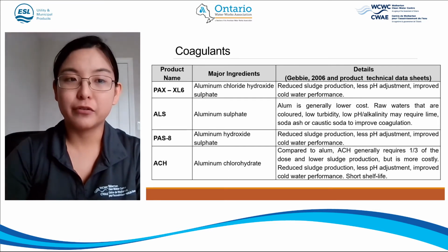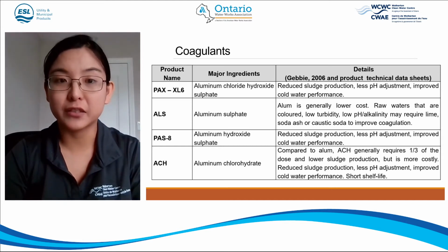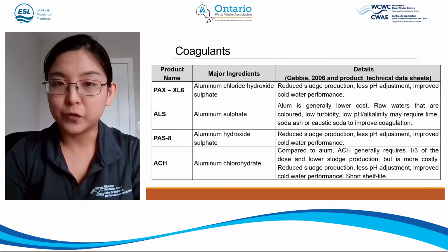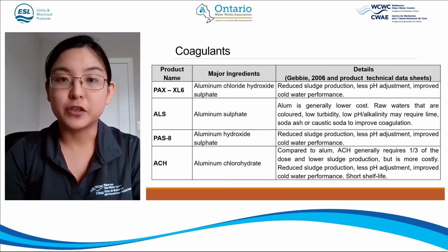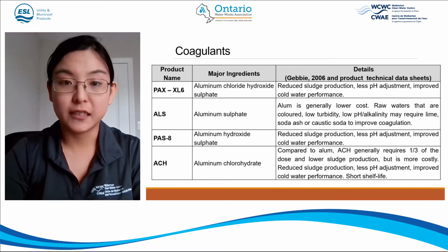So we also chose another 3 coagulant products that are improved for cold water performance, with less need for pH adjustment and less alkalinity change.